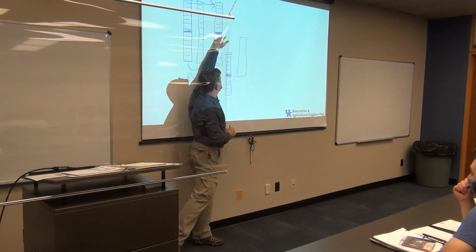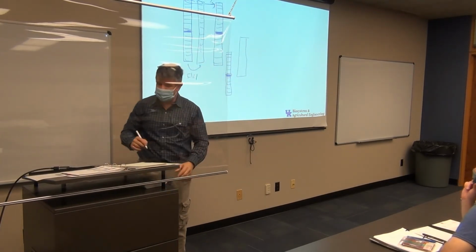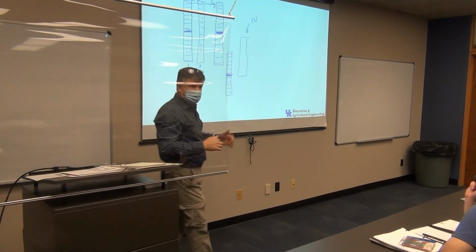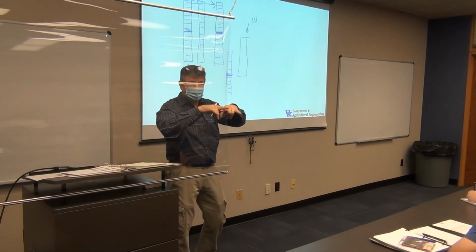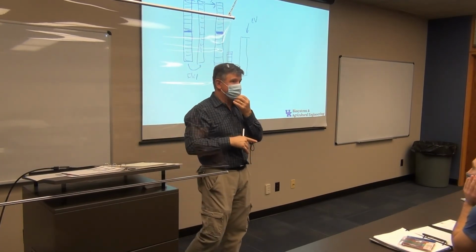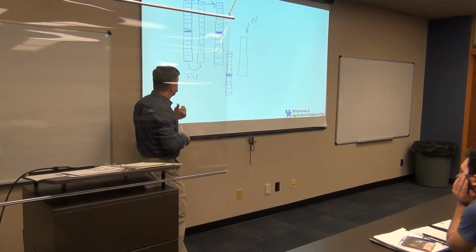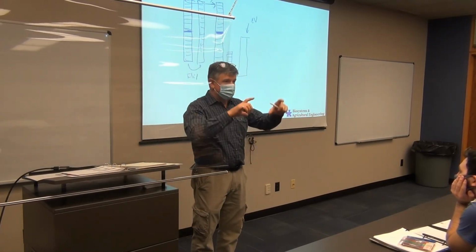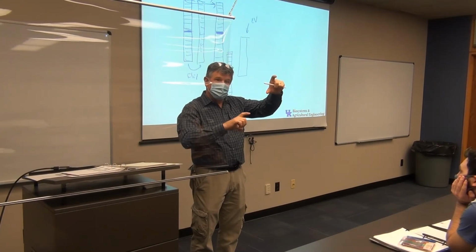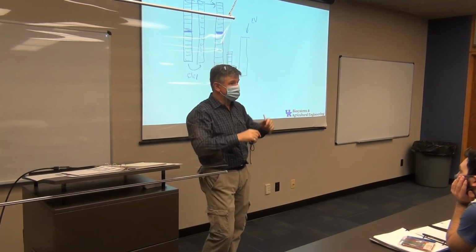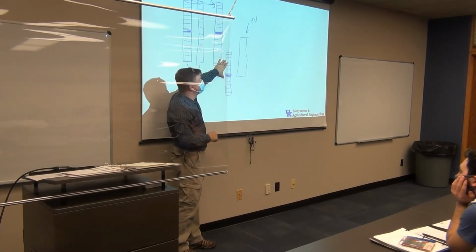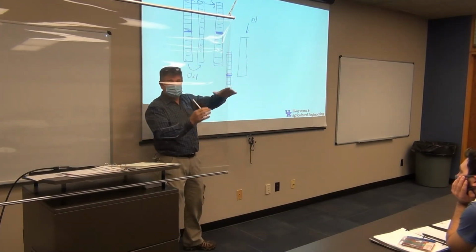I go from nozzle center to nozzle center, and then here, this is where I look at the CV on that column. So that's the overlapped coverage. That's what's actually going to be overlapped. And I look at the CV on that and say, is that CV good or not? And here's where you got to do kind of a repetitive process, an iterative process. So let's keep sliding that. So this is one spacing there. What's the CV for that spacing?